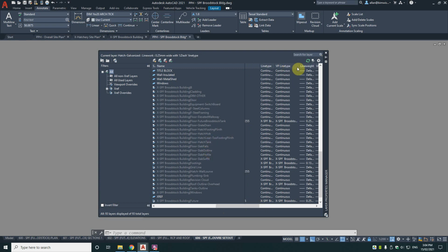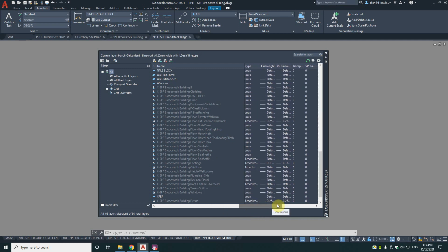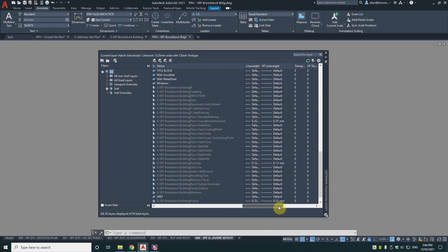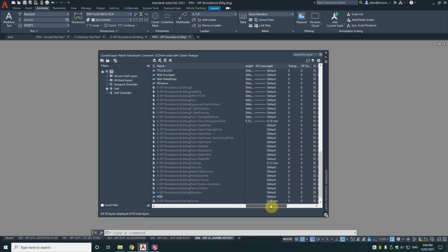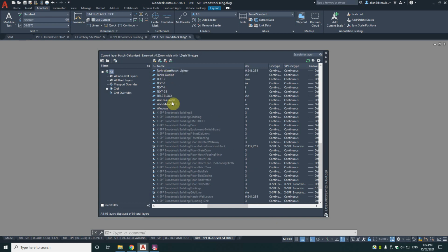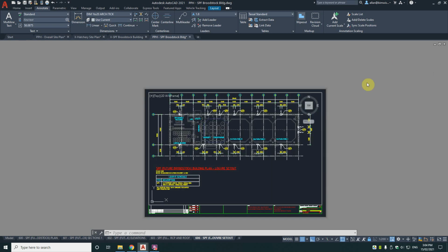You've also got, if you explore this more, a viewport line type where you can do an override just for an individual viewport, and VP line weight. So that applies not only to Xrefs, but to any line work that's in your drawing, but you can use it for both there. So that's how that drawing's set up. So that's the main architectural set.